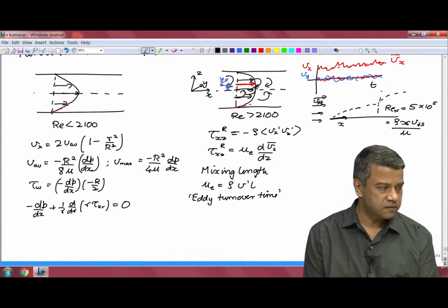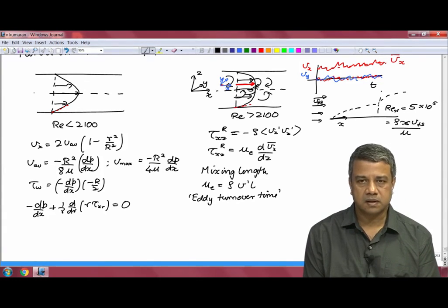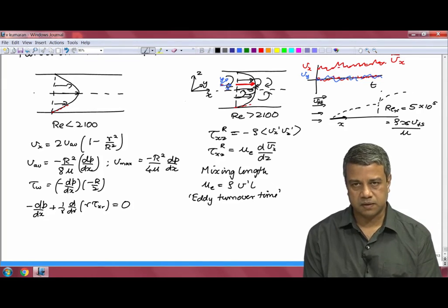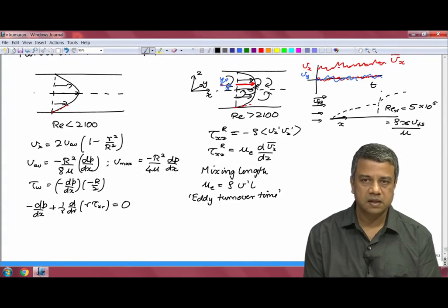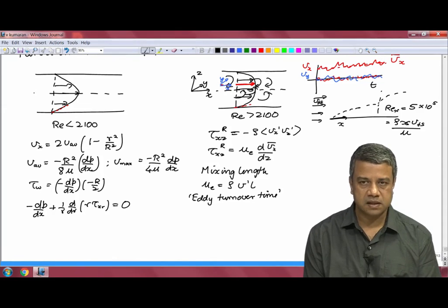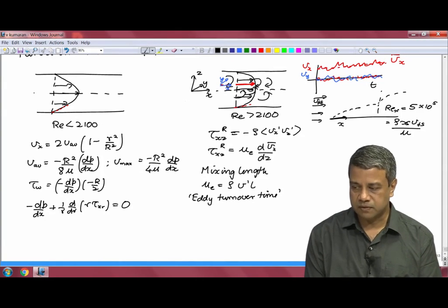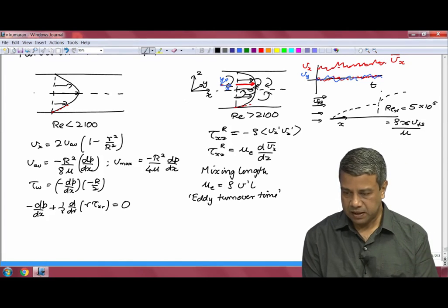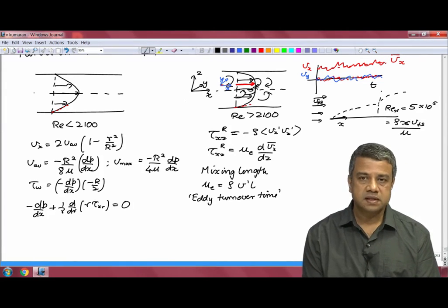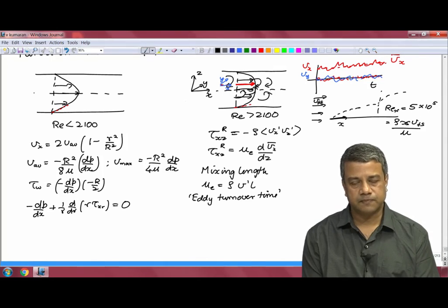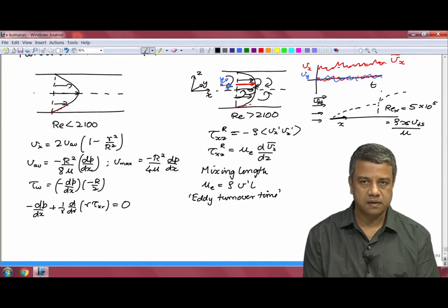And we also saw the flow around a particle, where turbulence formed in the wake when the Reynolds number increased beyond about 400 or so. Between 400 and 4000 you had oscillating vortices being shed at the rear side, and above about 4000 the flow became turbulent on the downstream side. So, this is a summary of our discussion of turbulence so far, when we looked at the different flow regimes in different geometries.